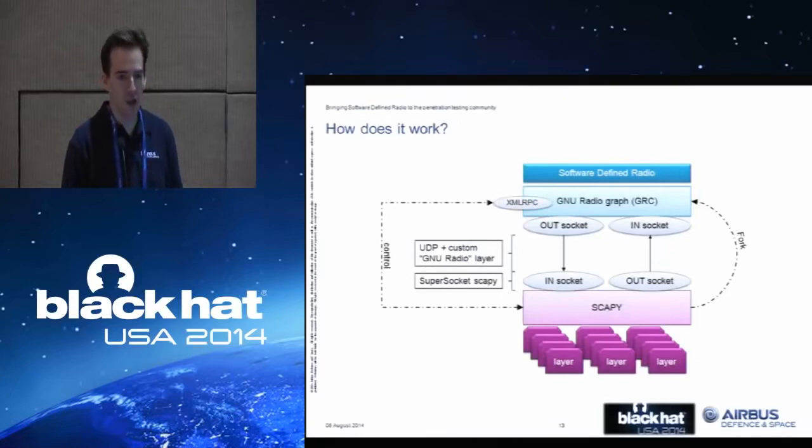Recently, we wanted to dynamically change the behavior of the GNU Radio graph. GNU Radio provides an XML RPC server that can be leveraged to do that, to change variables, and it will reconfigure your graph dynamically. So we added that channel.